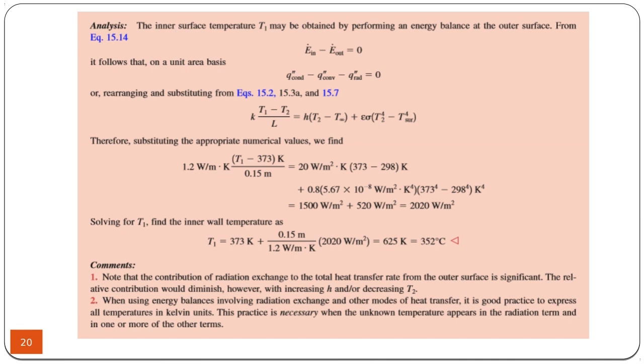Energy balance, E in minus E out is equal to zero, meaning that on the surface, incoming ones are plus, exiting ones are minus, which means conduction minus convection minus radiation is 0. So conduction is k times delta T over L. Convection is Newton's cooling law. Radiation is the Stefan-Boltzmann law. So if you put everything together, you have an equation, and by solving this equation,